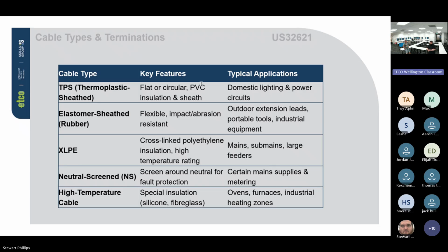So the general rule is double nut or double screw. So if it's going into a tunnel type with screws, you need 2 screws onto that. If it's going onto a post, it needs to have double nut. And at least all the inspectors I've worked with will get really annoyed if you put 2 lugs on one post. So make sure you've got enough posts for the amount of lugs you need to put on.